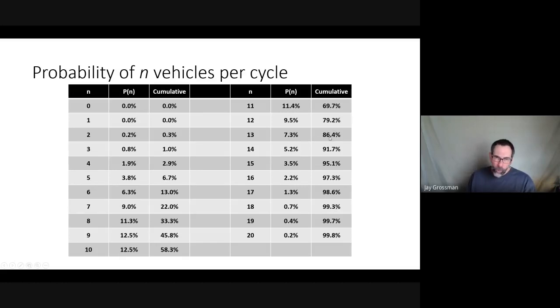Or more commonly, we go for the 85th percentile. So 85% of the time we have enough space for all the vehicles to be there. In this case, we'd have to allow for 13 vehicles to arrive. This is where we'd want an integer number, because we're going to design this lane to handle 13 vehicles. It doesn't help us to design for 12.9 vehicles, right? That doesn't help. We just have extra. We have 0.9 extra space that no car can fit in, right?